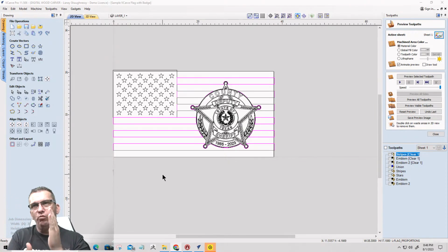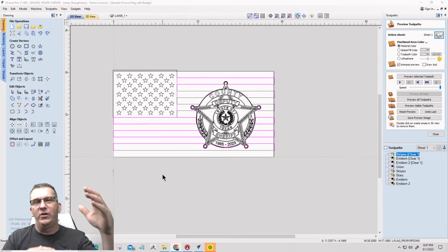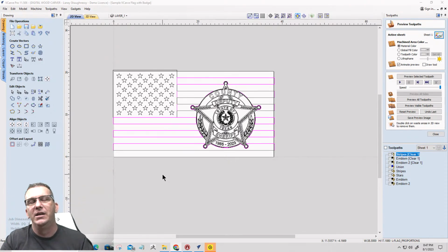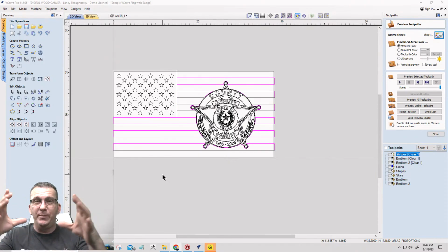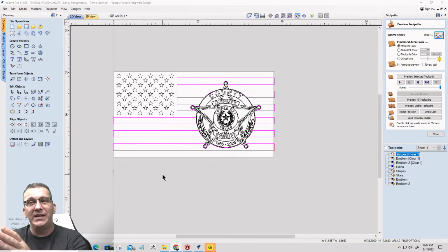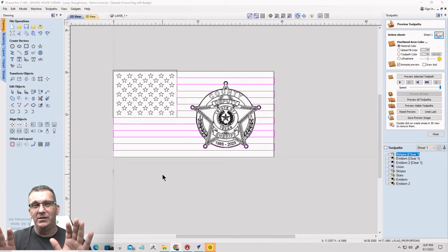Now, rule of thumb. Larger diameter, slower the speed, right? So let's say I'm working with a 1.25 inch surfacing bit, okay? For me, anything kind of over 1 inch, I start slowing things down. With a 1.25 inch surfacing bit, we're going to be probably running around 14 to 16,000 RPMs. I generally run mine at 16,000 very well. But we're going to be around 14 to 16,000. Now, you get up into your 2-inch diameter bits, and for any of you mid-size and hobby units out there, your surfacing bit should not be any bigger than 2 inches.